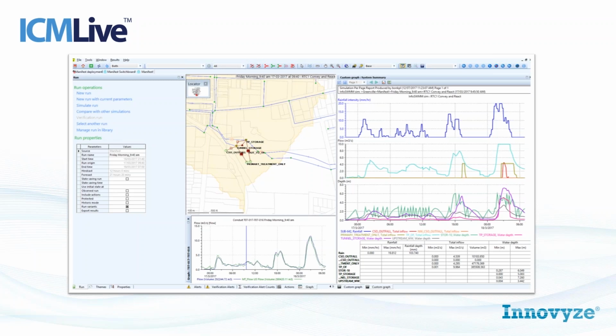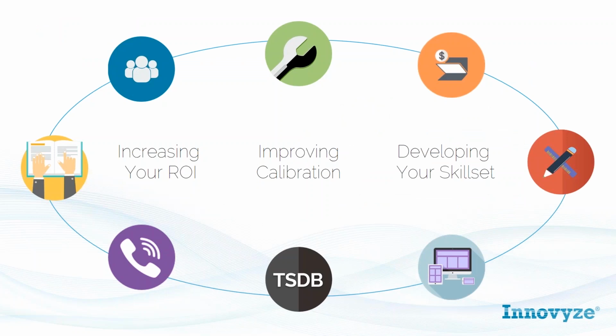Operators often come over to the planning engineers and they ask, how much time do we have until failure based on storage availability? So you get more engagement with the models. They become more valuable to your organization. So you can even use that information to help with setting alarms and critical alarms in your network. So if you've got a few hours worth of storage before you get an overflow following a pump failure, you can use that to inform when your critical alarm should kick in, which can be good for preventing operators having to get up in the middle of the night to address an outage somewhere that maybe they don't need to.